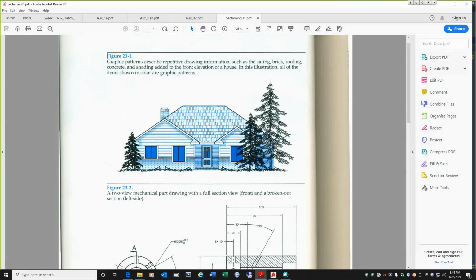We've got transparency. So anything that's this solid blue here, which should be this shadow line, this window, and this little darker blue in here, those are all the same solid color hatch. What makes those different is the transparency level. The higher the transparency level, the less intense the color looks. So it gives us a whole other graphical element to show shadow lines, or think about why this is a little darker here. I'm going to pause and say, do you think you know why that would be in this type of a drawing?